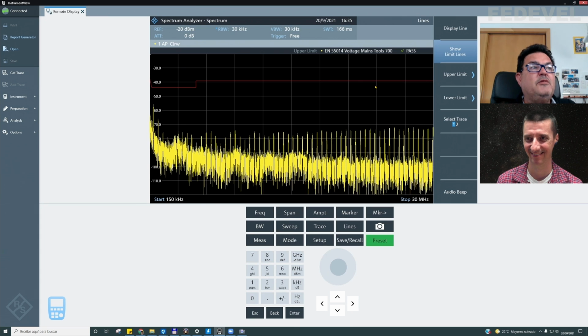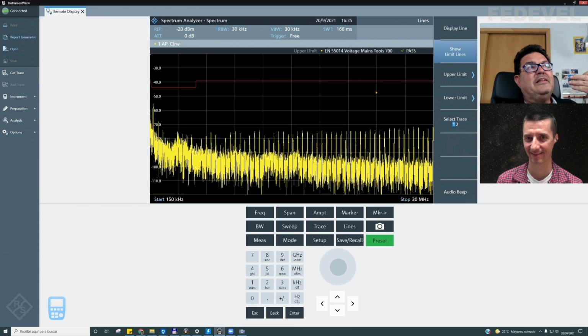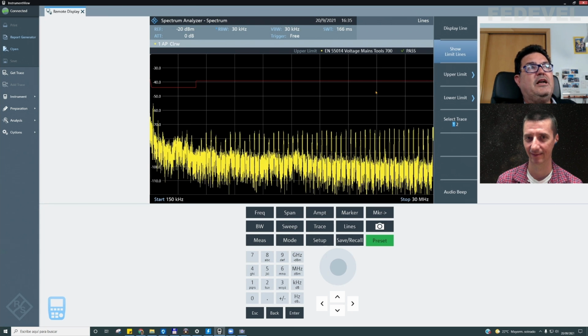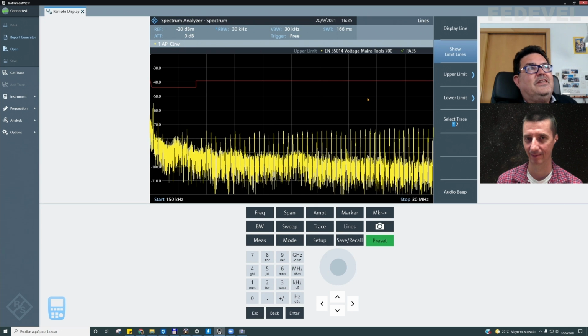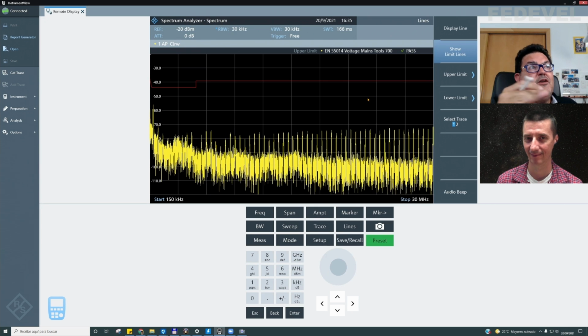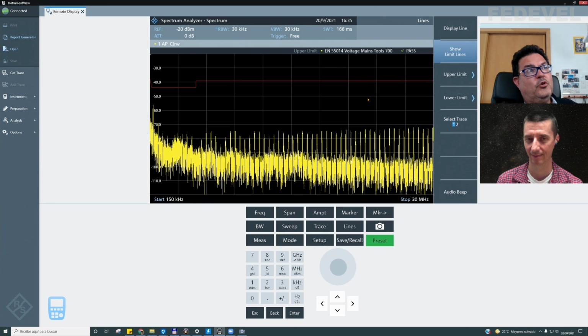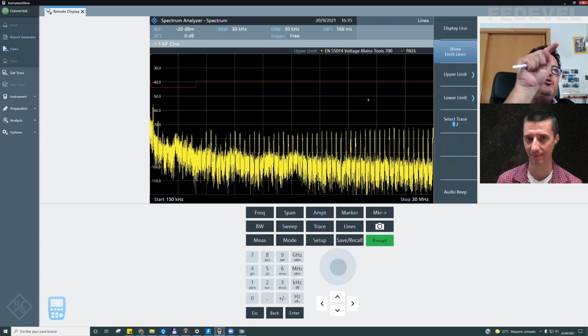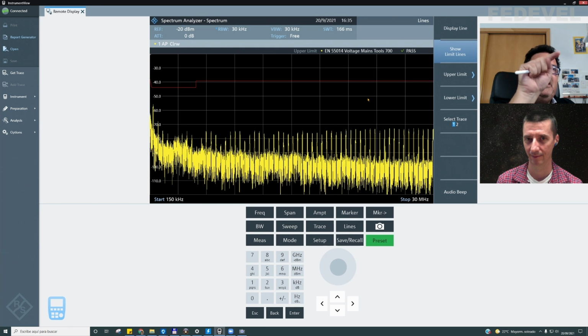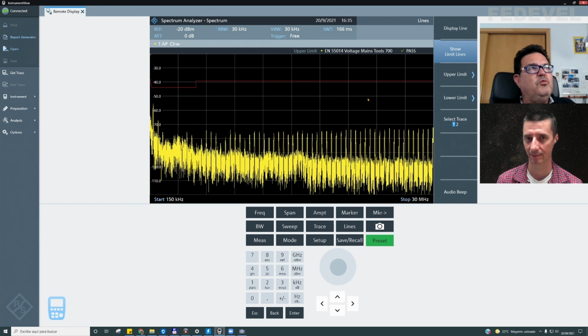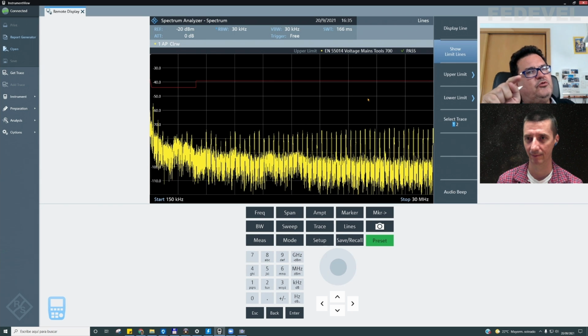You will see the noise at some specific value, and you can try to work to reduce this value 10 dBs. So you will be working in a good way, because the reduction you obtain is what you want at the end, but you will not be able to be sure how the peak of the signal compares with the peak of the signal in the external laboratory. This is the idea.